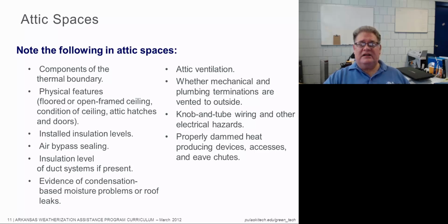If you have duct systems, like we do here in Arkansas quite a bit, if you have HVAC ducts that are running through the attic, are they insulated properly? A lot of codes require a higher level of insulation for ductwork that is in the attic than for ductwork that is in the crawl space or another area. Okay.